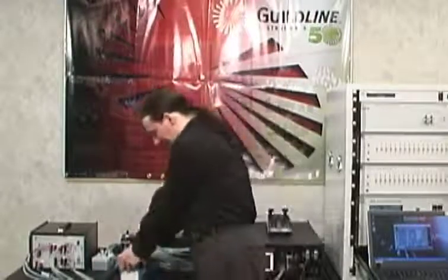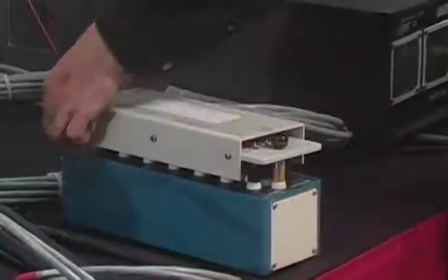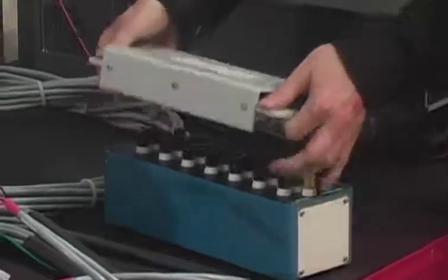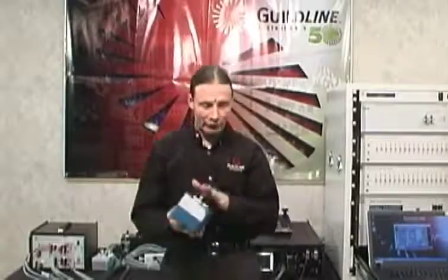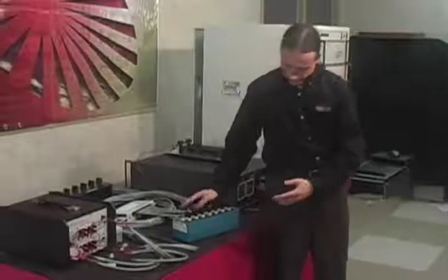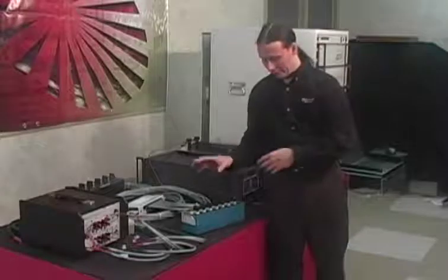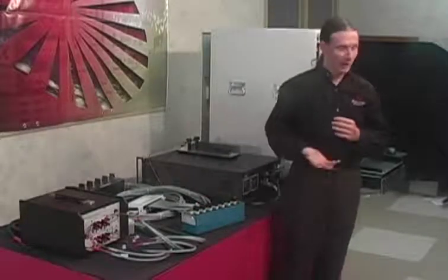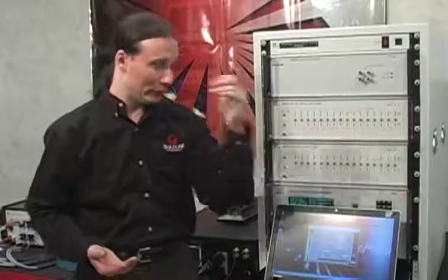Once you're complete with this measurement, then you'll have to disconnect this device, and these 2 thumb pressure points here with the black valves on is how you can help lift this adapter off. It comes off quite easily with that. And then you'll take your SR1010 and you'll reconfigure it for a series parallel measurement using the shorting bars that come with the SR1010, and make the measurement over again in the utility just by clicking the go button over here. And you'll have to connect, of course, the series parallel adapters to one scanner channel, and by default we have it set to the channel 32, but it could be any free channel that's available from 26 up to 32.